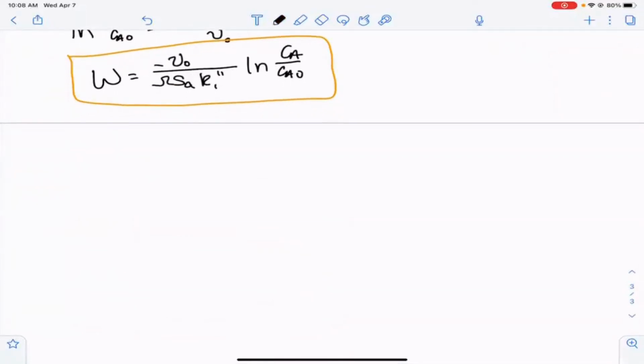Now, if you remember, in our last lecture, we had a definition for the overall effectiveness factor. And we said that that's equal to the internal effectiveness factor divided by 1 plus the internal effectiveness factor times K1 divided by KC times AC.